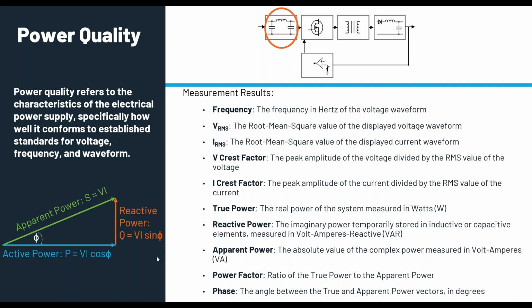And yeah, there are other factors like the crest factor, for voltage and current, and also we'll be looking at the RMS values of these currents and voltages. So these are pretty important basic measurements for the input section. We can do it manually also, but nowadays many of the scopes have this as part of the standard measurement package.